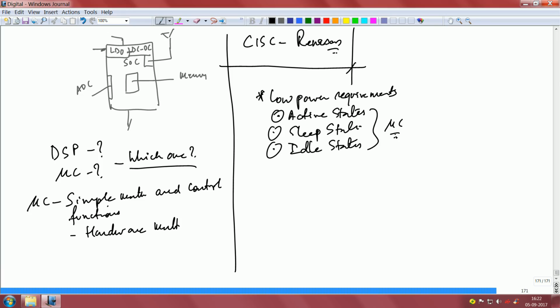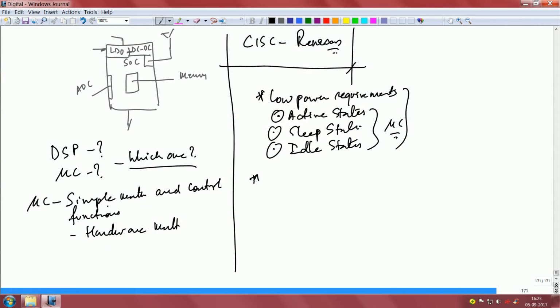Okay. You must study them in detail, find out what is the current consumption purely from a microamps per megahertz specification perspective. So, this is very important. So, look up that performance and maximum frequency. Okay. Performance and maximum frequency. Here you will be stuck in many ways.